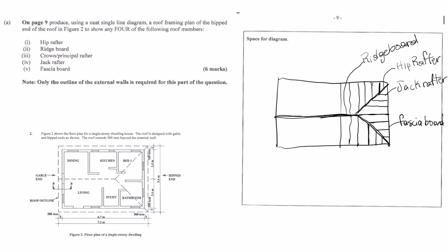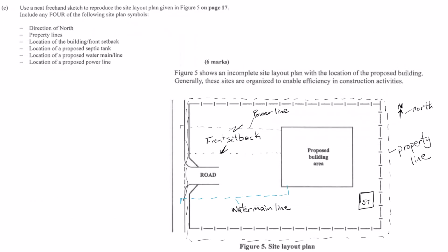Okay, let's zoom out even further now. How does the building actually sit on its plot of land? We mentioned a site layout plan. What's the main point of that drawing? The main goal there is to show exactly where the building goes within the property lines. It gives really crucial info about the building's position relative to, well, everything around it. Boundaries, roads, maybe existing trees, utility lines. So it's like the map showing the building's specific spot on its own piece of land.